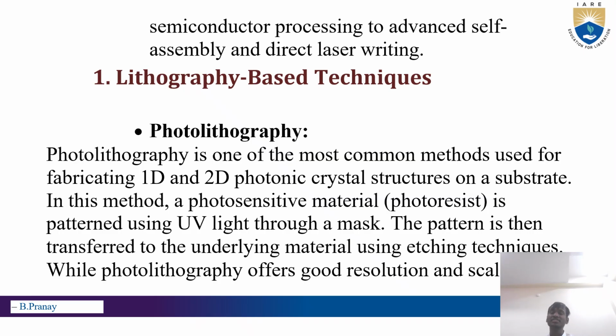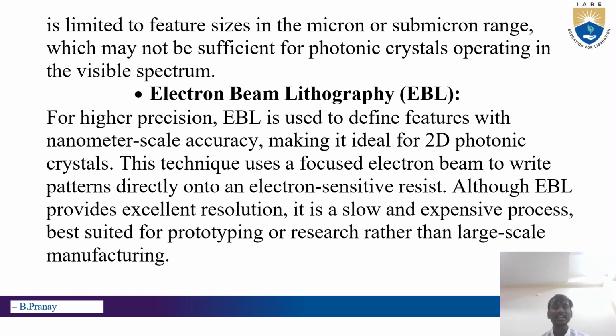Photolithography. Photolithography is one of the common methods used for fabricating 1D and 2D photonic crystals on a substrate. In this method, a photosensitive material is patterned using UV light through a mask. The pattern is then transferred to the underlying material using etching techniques.